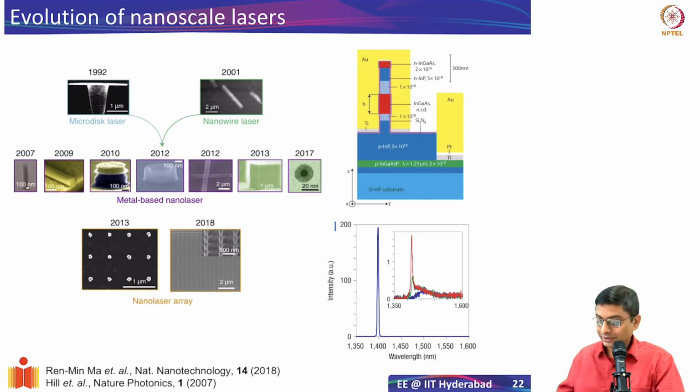And in fact, if you see this, the bottom contact, so this is my nanowire. The lasing should happen from this red region, and everything else is basically the P-type contact and N-type contact. So you'll see that you'll have electrons from the top here, and the bottom is actually from this side. You actually etch out what is called a mesa, and then you make a contact with the bottom layer, and from that you inject holes into the structure. And from the top you have the electrons which are injected. So it's a beautiful piece of engineering that actually gives you this.